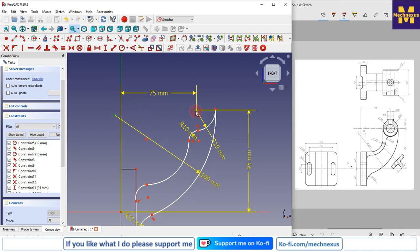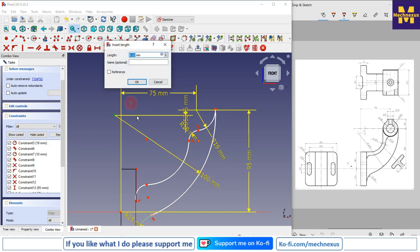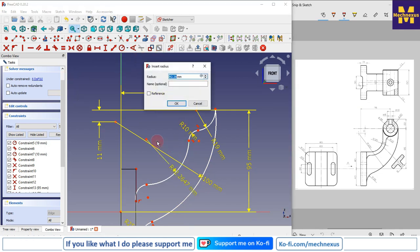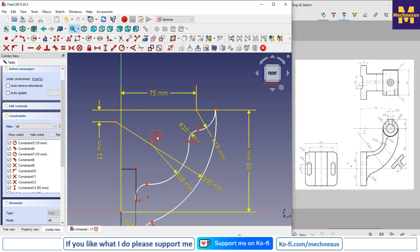I will select this point and this point, and give the vertical distance 11 mm. I will move the dimension to the outside, and this radius is 38, so I will give it 38.